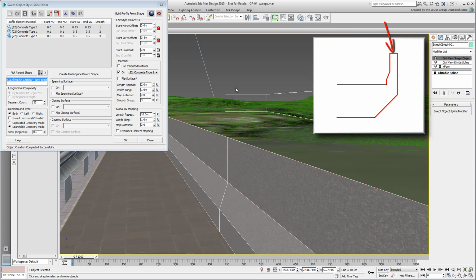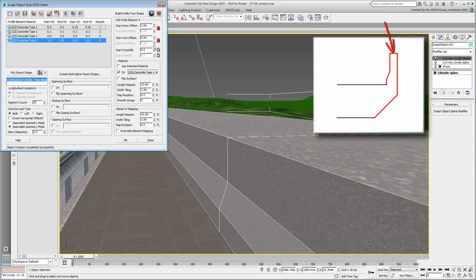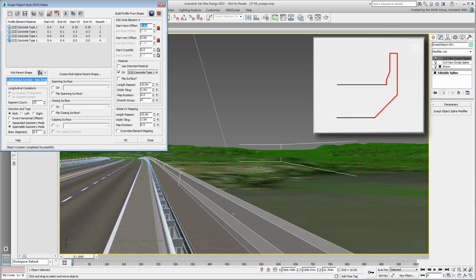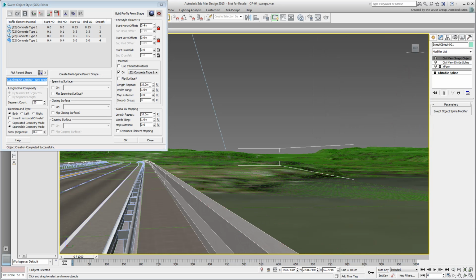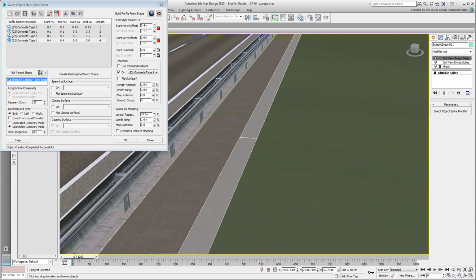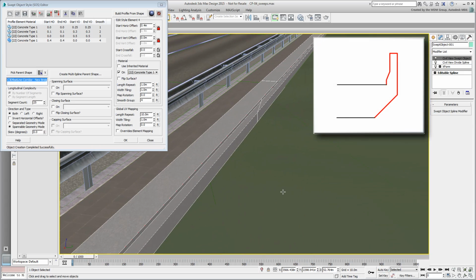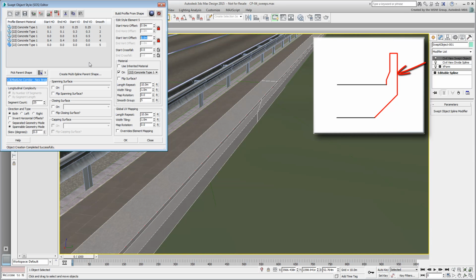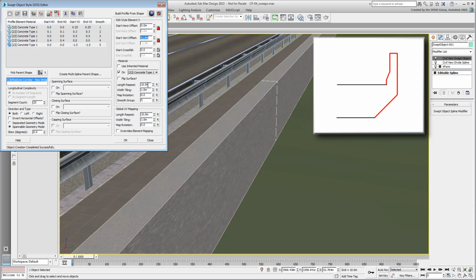Add another element for the top of the wall. Stretch it out by 0.4 meters with no height. Adjust the mapping. Now you need to come down on the other side. Add a new element and set it to go down by specifying minus 1.5 meters. Adjust the mapping.